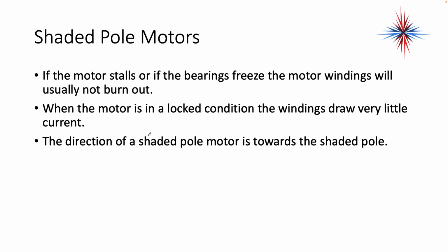If the motor stalls or if the bearings freeze, shaded pole motors will usually not burn out. When the motor is in a locked condition, the winding will actually draw very little current. The direction of the shaded pole motor is always towards the shaded pole.